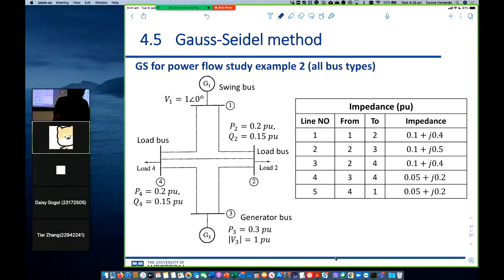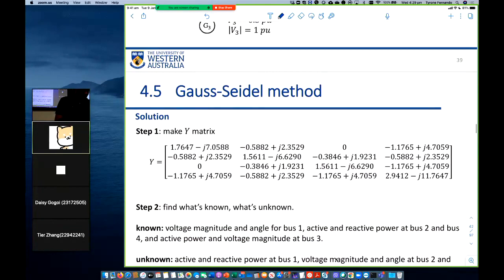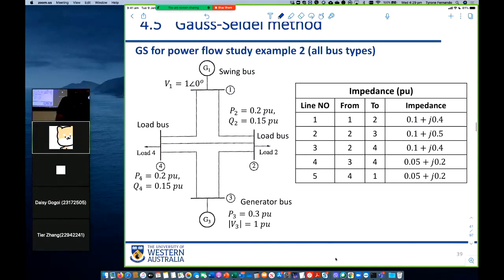So, when we are looking at the admittance matrix Y, for this element here, we need to consider all the lines connecting bus bar 1. So there will be one line here. We need to consider this line and that line. We need to find the admittances of those two lines that are highlighted in red, and add them.